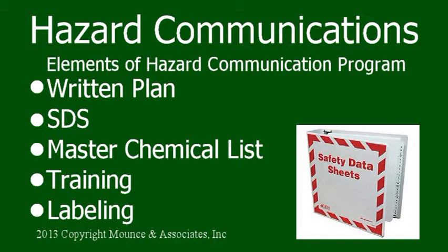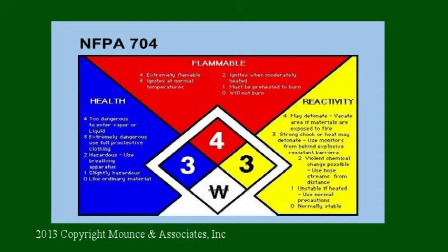Every chemical needs to be labeled. This is an NFPA label. Blue is for health, red is for flammable, yellow is for reactivity, and white is for special.